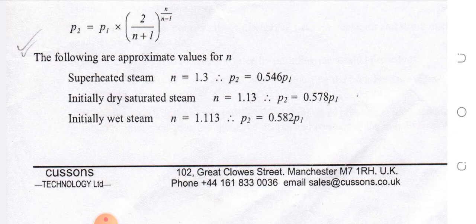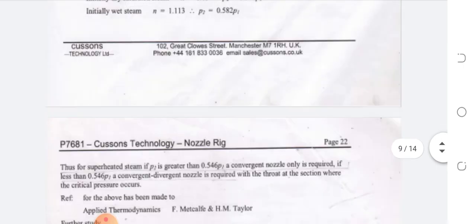And after reducing the pressure further, we don't have an increase in velocity, because at the throat we have a maximum sonic velocity, that is equal to the speed of sound. So after reducing pressure from 4.62, the velocity will not increase. Similarly, the flow will not increase. So this is called a choke flow condition.